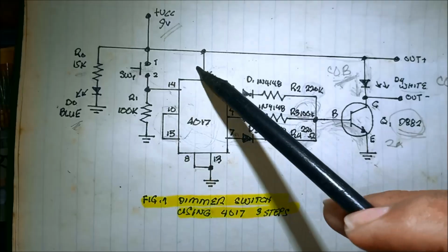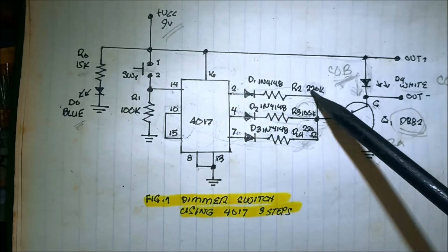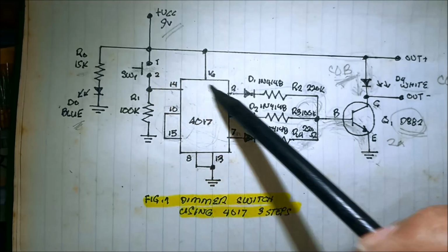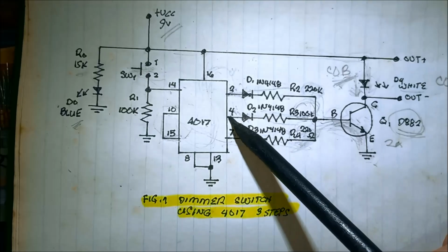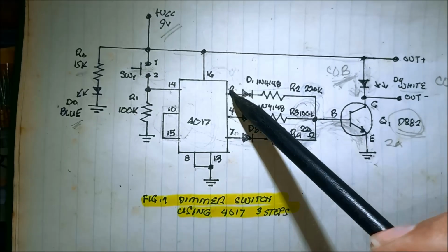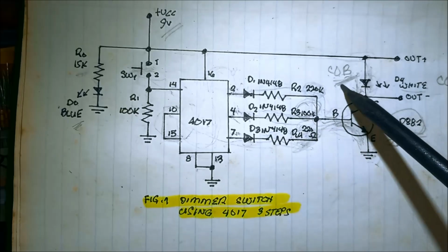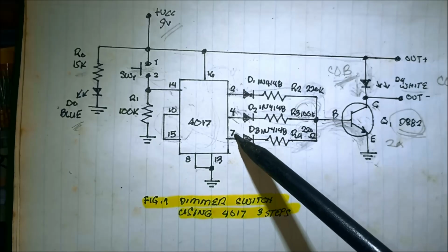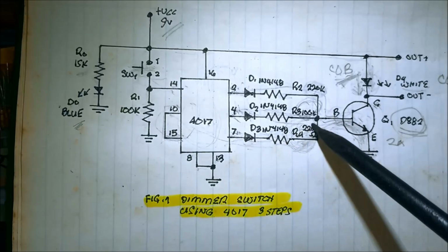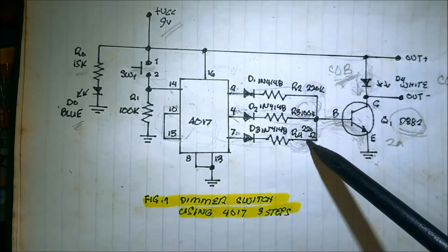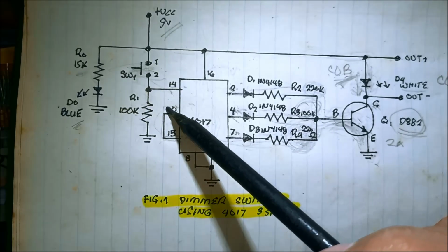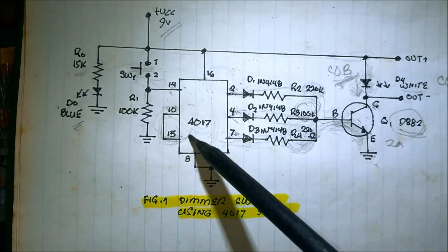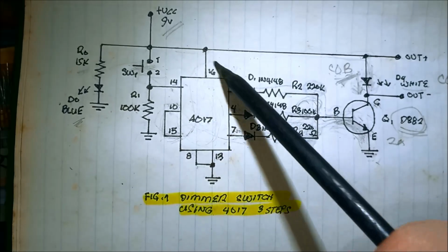So again, we press it again, it will turn on pin number 2, and then we have the dim LED. Press it again, it will turn off, press again, it will turn on. Now this one is off, this is now on, for a much brighter light. Then press it again, it will turn off this one and turn on pin 7, the bright light, because of less resistance value. And then press it again, it will turn off, reset again, and cycle back to pin number 2.